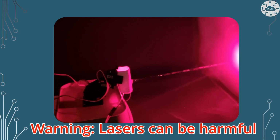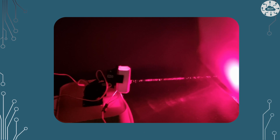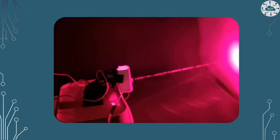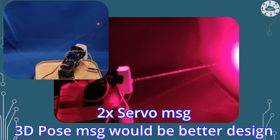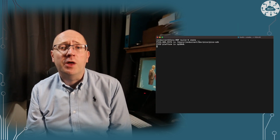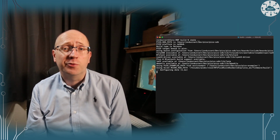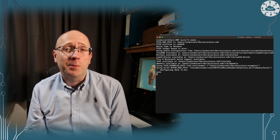Of course, if I can run one servo, then I can run several. The Pico will support 16 PWM channels and therefore 16 servos. I'm just going to run two with a little pan and tilt model with a laser diode to make it look a bit cool. Though I've only shown a custom message in this video, we could use the same approach for the two other communication primitives of services and actions. Needing to rebuild the whole firmware library for MicroROS for each new message type I don't think is ideal. What do you think? Is there a better way to do this?